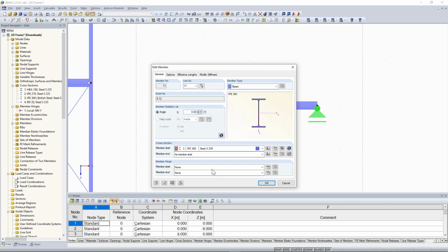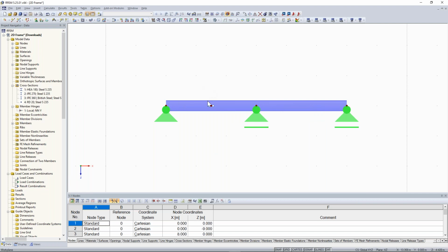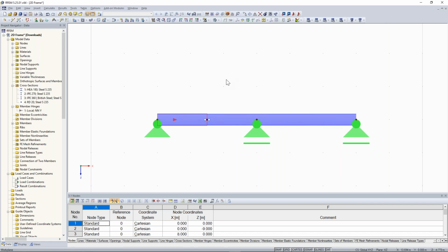No additional adding here on this side, because this would end in an instability, because you have here too many member hinges, and this would lead to a calculation error of the program. So remember, when you have 3 member hinges on one node and also 3 members which connect on one node, then you have done something wrong, because this isn't possible.